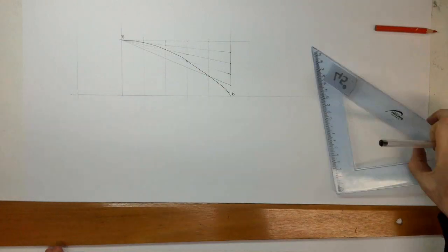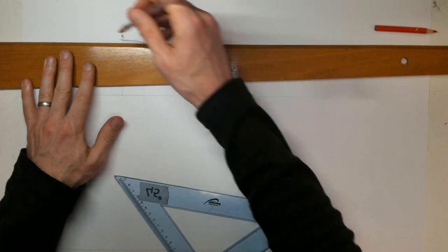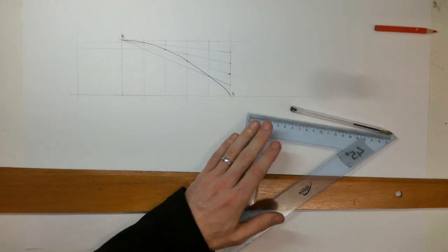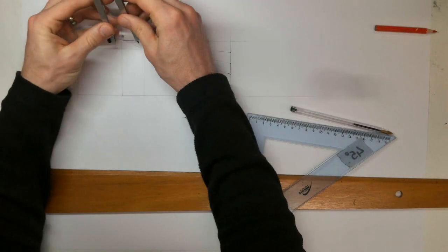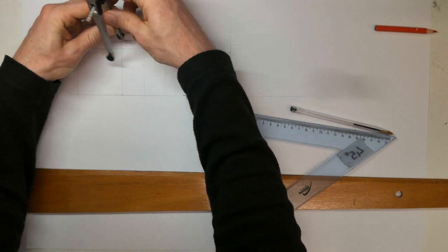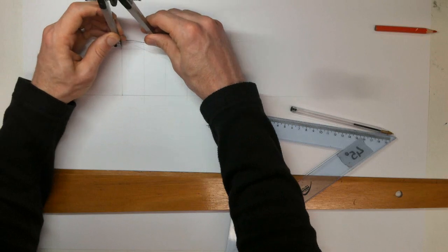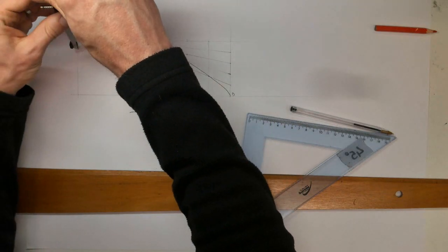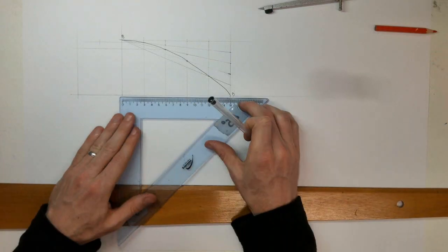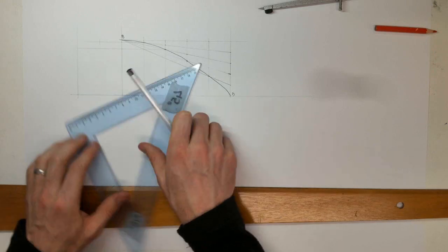And then we're just going to project across using axial symmetry. So point to the compass, set to 30 actually, so that'll find me a new point, and then this is set to 60, which will be in line with that. That's making life very easy for me, because that's 60, and this is also 60.